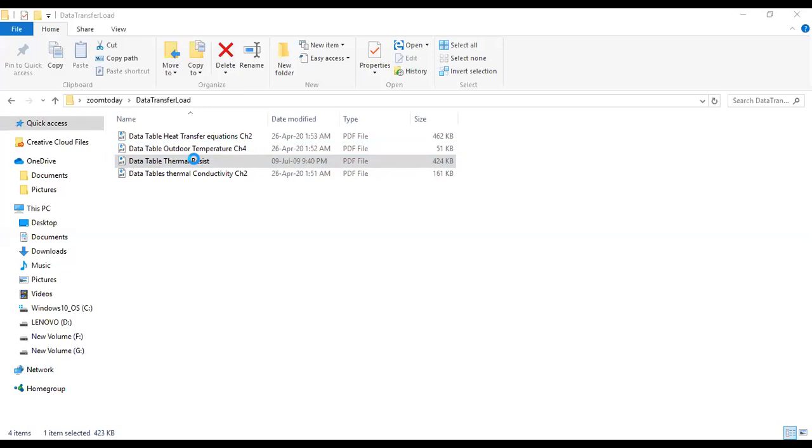So now this is U factor, this is resistance R, the reciprocal of U factor, in meter square Kelvin per watt. You may use this if thickness is mentioned here. If thickness is not mentioned here, you take this and multiply with the actual thickness in meters, not millimeters. Thickness is usually given in the problem in millimeters. You have to convert it into meters, divide by 1,000.